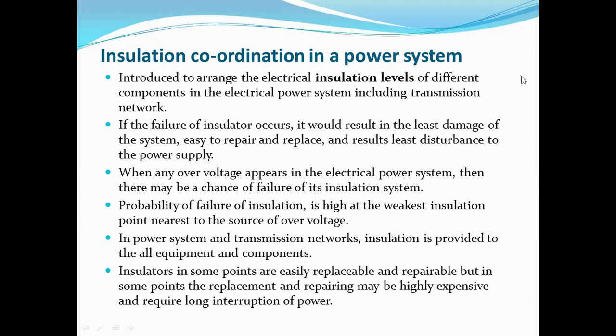And its repair is very costly, because we know that there are 220 kV transmission lines, and these towers also have six lines. If that tower gets affected, then whatever supply is provided to the load, that whole system will stop. So to protect that system from these over voltages, we have to do something.